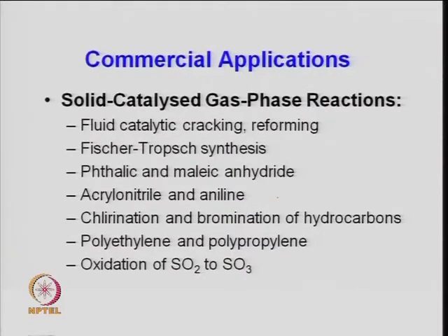One is the solid catalyzed gas phase reaction, where they are widely used. One of the most important is FCC cracking. More than 420 FCC reactors are available worldwide, and they are producing a large amount of gasoline from heavier feedstock. Larger molecular weight hydrocarbons, which can be C20H42, something like a paraffin hydrocarbon, a crude oil fraction, are cracked to a product like C10H22, which is towards the gasoline.